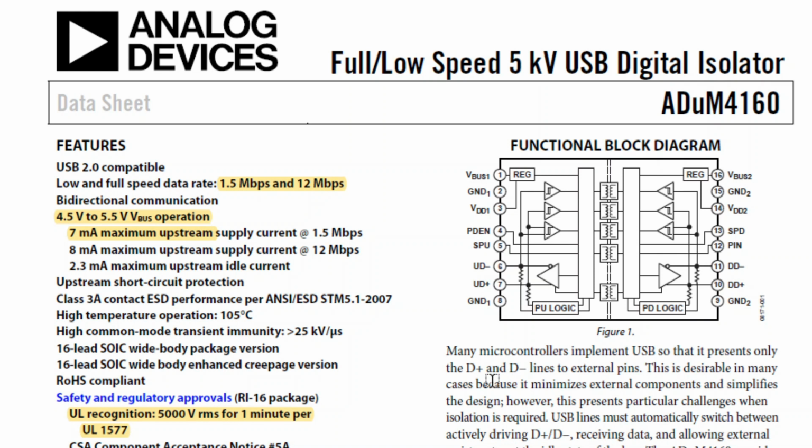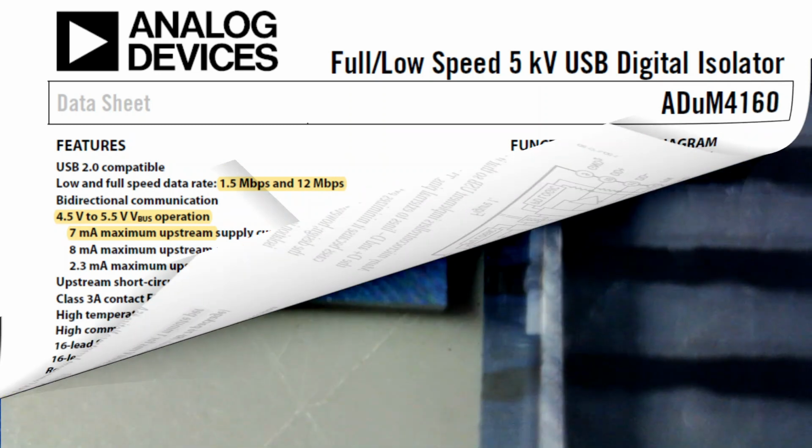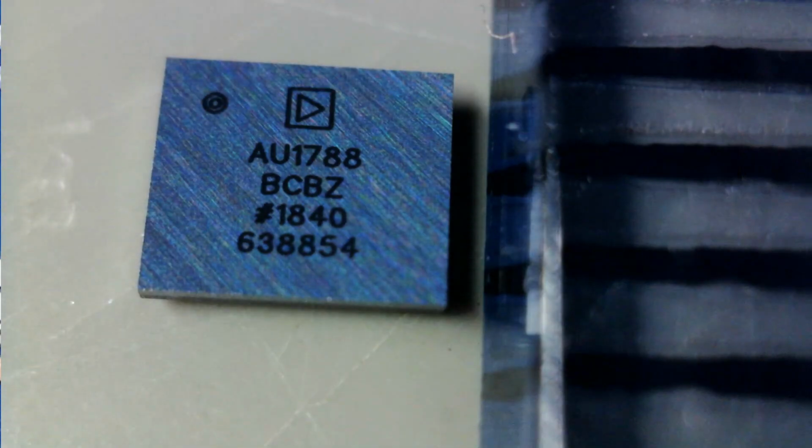and these are also driven by USB to serial converters, and of course the radios connect to aerials on the outside of the house, and what I don't really want is some sort of static build up on the antenna or things like that getting back into my PC. So the idea is one of these will sit feeding the USB to the radio's RS-232 converter. As you can see, these are very small chips, just over 2mm square.